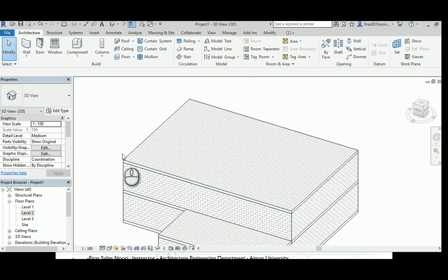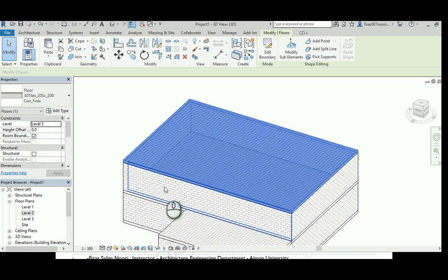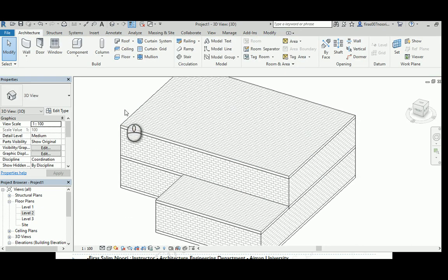Now this one, again, inside is finish 5, but on the side face on, we don't have any layer beneath the slab, so it's okay. Above it, it's finish 4, so you have to change this to the second type, because it's finish 4, facing exterior, sorry. So be aware that you might have more than one slab and more than one type of slab when you design the whole thing.